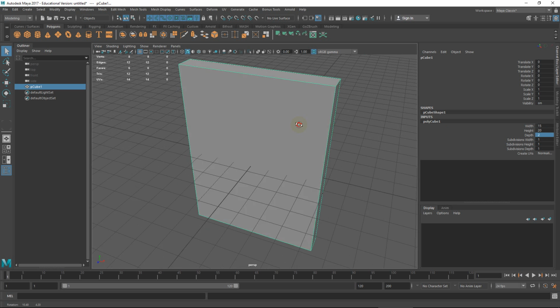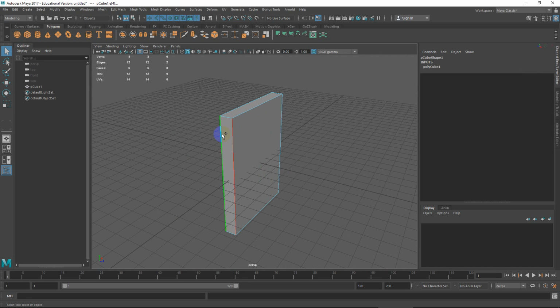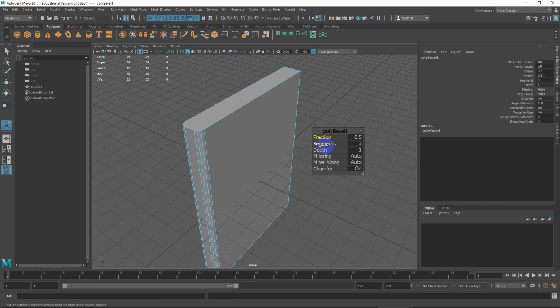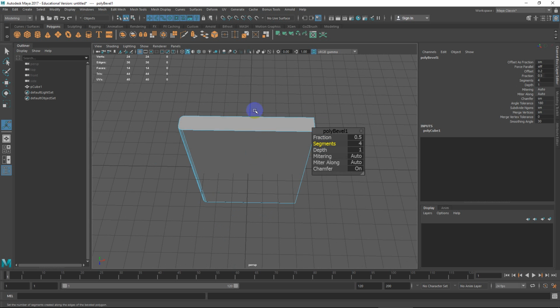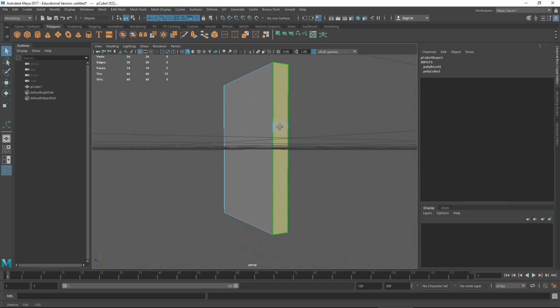That's okay. So I'm very quickly going to edit this. So I'm going to grab this edge and this edge. Bevel this edge. Again, if I'm going to have a lot of books, I want to be careful not to necessarily add too much in the way of mesh, but enough so that I get enough information. I'm going to go to face mode and grab these 3 faces.